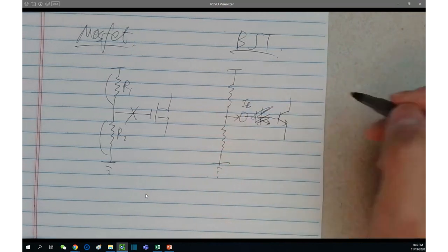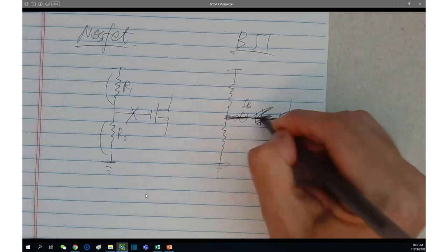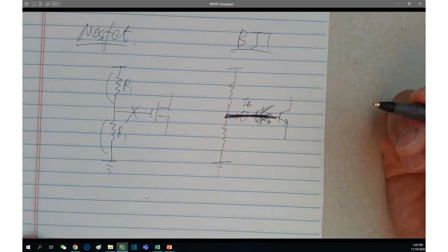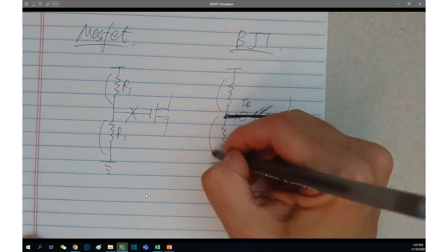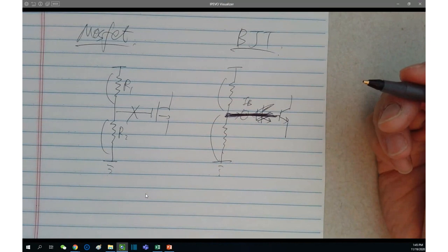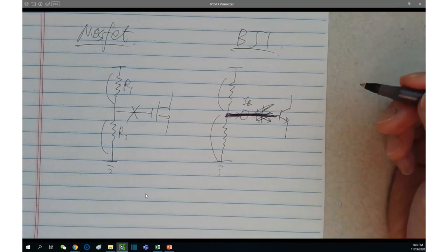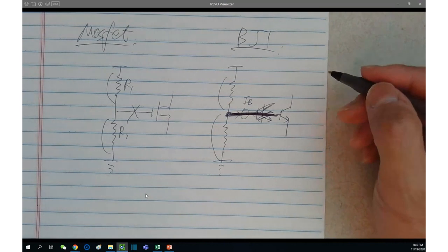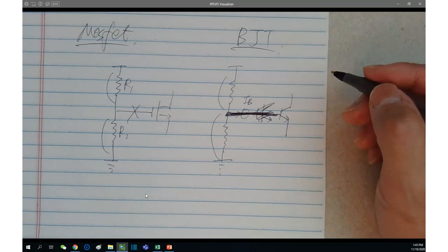You have a current flowing here, in the middle, in intersection with another path. Are you doing a voltage divider between these two? No, you can't do this. This is wrong. Does it make sense? This is why you can't do this voltage divider. It's not allowed. Then what can you do?